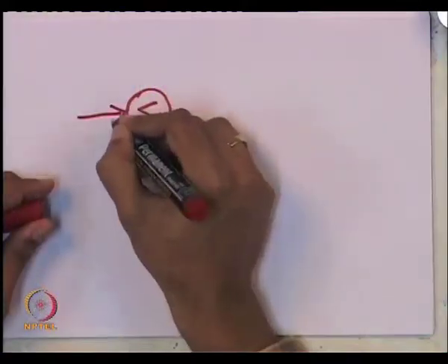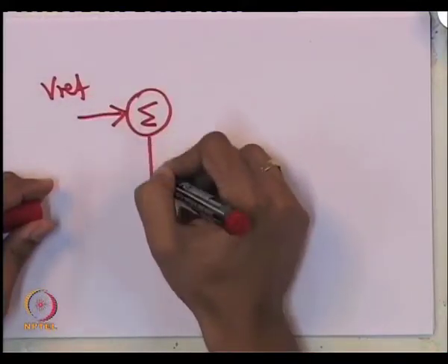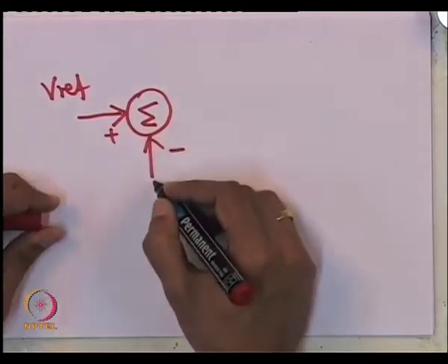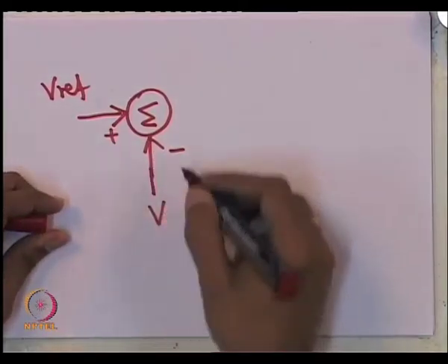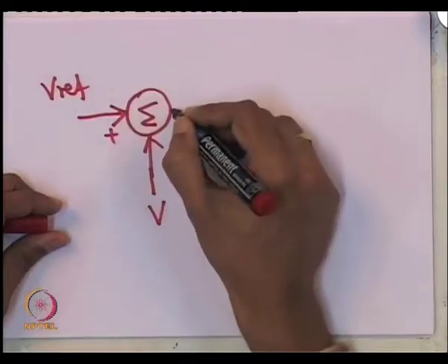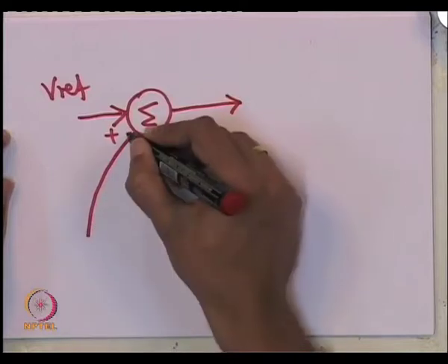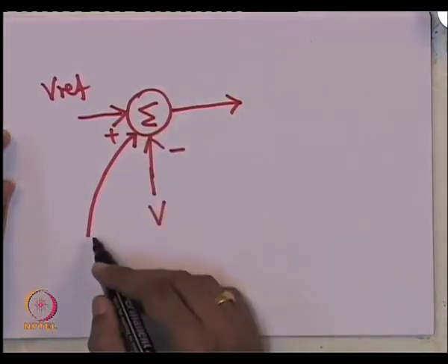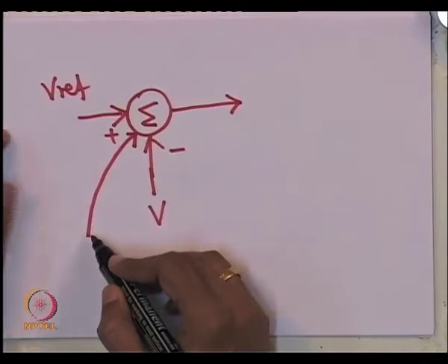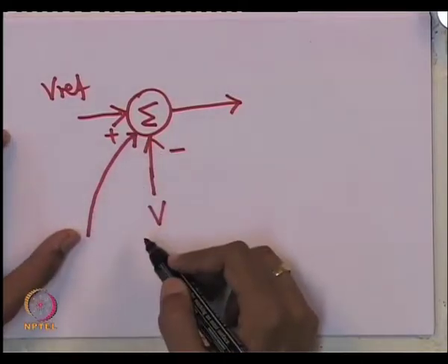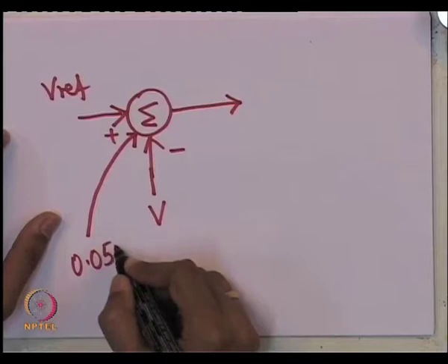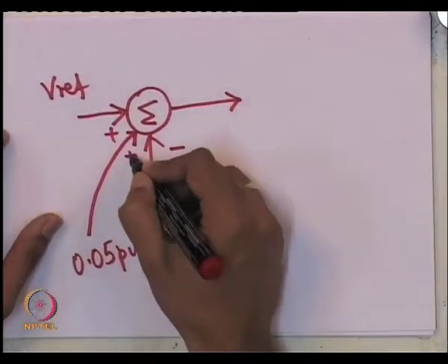So, what you have usually is the stabilizing and limiting functions. What you have normally is Vref, and in case the generators are not bused together right at the terminals, this is the structure of the summing point of the voltage regulator, but Vref itself may be overridden, in the sense that some additional controls, for example, if I put some additional input here, say 0.05 per unit, I add at this point.